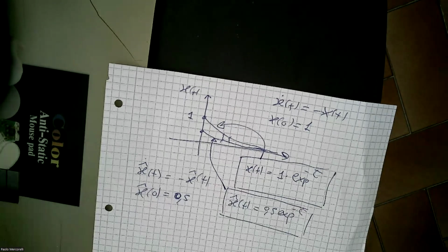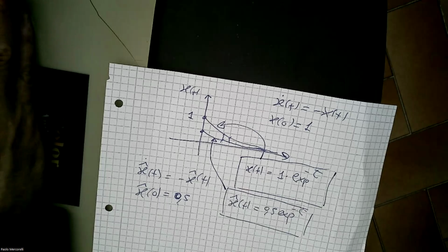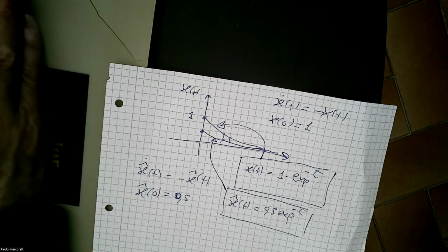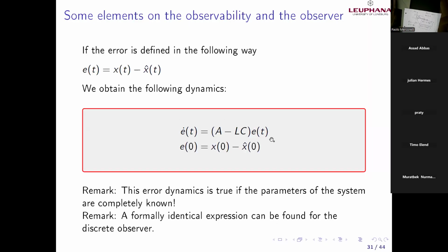But of course, we have to work also in this case on the observer. Let me remain on this, and let me now go in depth a little bit here, if you remember in math. This equation here reflects exactly the dynamics of the estimation error, and in accordance with the eigenvalues of the matrix A minus LC, I can speed up or slow down, but basically we try to speed up, because in order to observe what happens, the observer must be faster than the system.